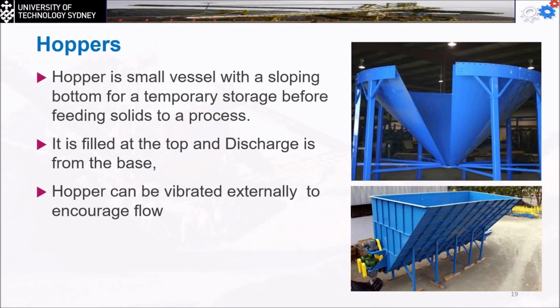Sometimes the hopper may be vibrated externally to encourage the flow, because we talked yesterday about the build-up of material on the wall. So the vibration is going to be the best option to empty it faster.